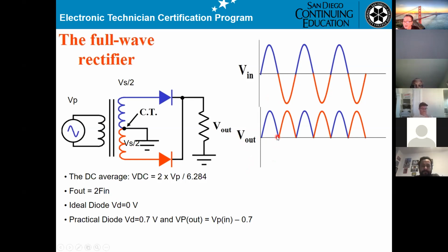So basically the half wave of the input here means the period at the output will be half the period of the input. So they're telling you the output frequency will be double the input frequency. If you get 100 Hz on this input here, the output will be 200 Hz. Okay, everything they already explained in here.